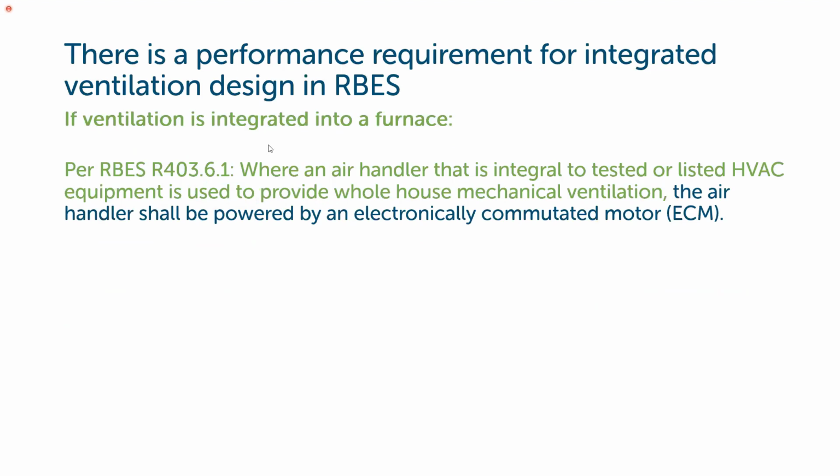And specifically in the code, if you are going to be integrating ventilation equipment, HRV, ERV, into a ducted heating system, section R403.6.1 requires that, as I mentioned earlier, the HRV or ERV has to have an ECM motor.